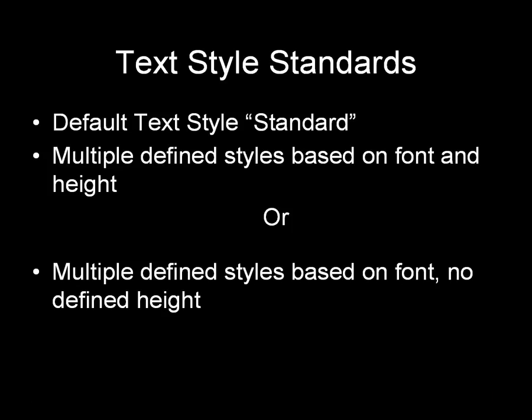Basically, and here we're talking really strictly AutoCAD or IntelliCAD. But when we start adding in that Carlson variable, when you use and have to create text using the Carlson commands, Carlson actually introduces 2 more settings that, the way I say it is, it works with and sometimes against the AutoCAD text style or text commands. And I would have to say, and again, someone from Carlson may want to chime in at some point on this, but Carlson is really meant to use this option too. So setting up a text style with that font is going to work best. Not that it won't work the other way, you just have to look at all your settings.